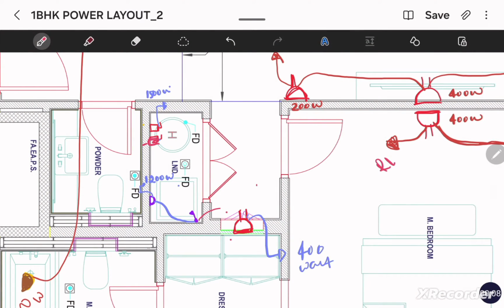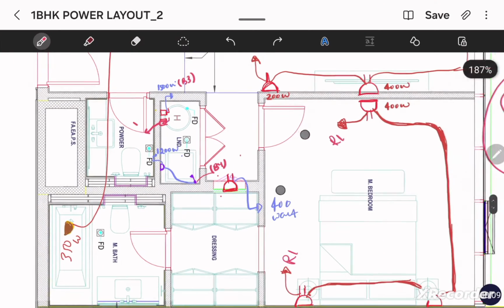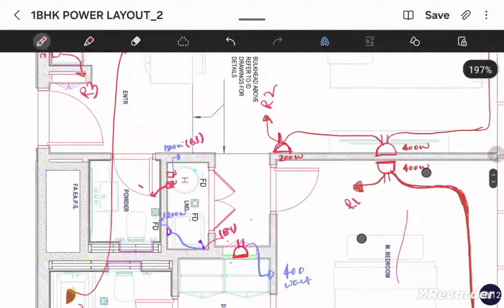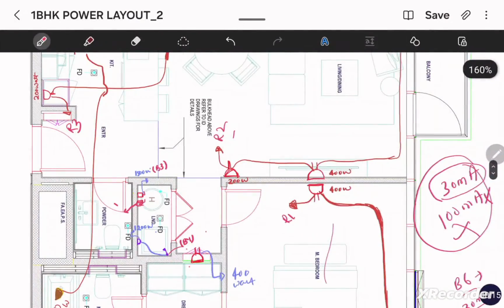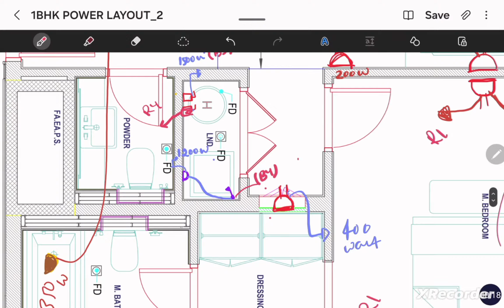Okay. After the kitchen, let us move to the laundry area. For the water heater, we will write the circuit number B3. For the washing machine, we will write the circuit number B4. Okay. And after the trial and error method, I found that if I write B5 here, then the load becomes imbalanced. After trial and error, I came to the conclusion that it should be a red circuit. As I have given the circuits for the red as R1, R2 and R3, this will be R4 and the ONU socket will be R5.